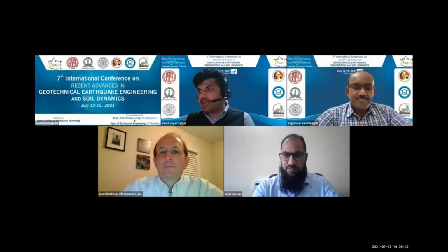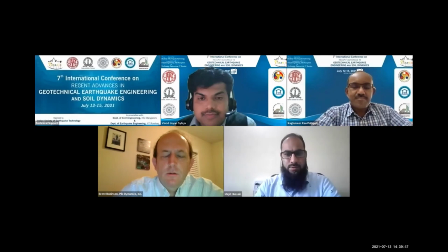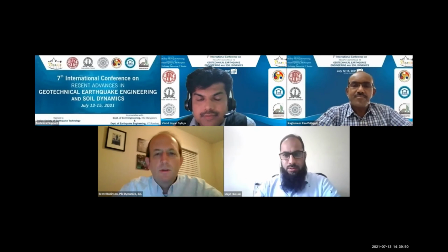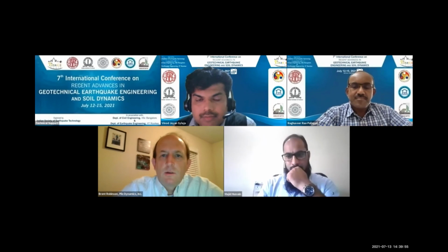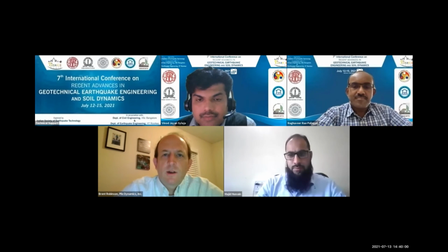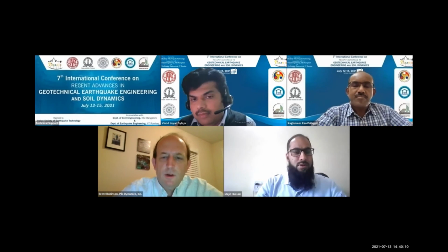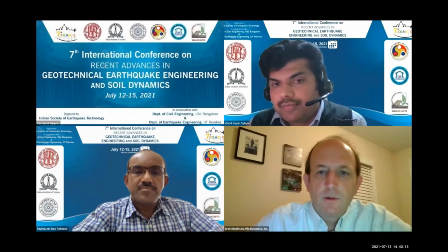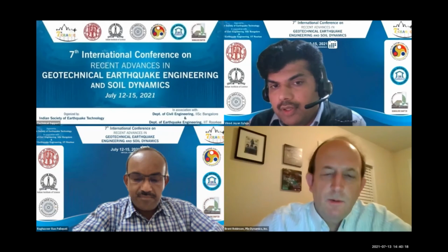Thank you, Dr. Vinod. One question from me. How much of the difference that you're seeing in the laboratory studies is an effect of the reinforcement aspects of the Coir Geotextile versus any separation or filtration effects? Are these grid-style Coir that you're modeling, or are these more of a textile that would provide more filtration and separation to prevent migration of the fines from the clays up into the gravels?